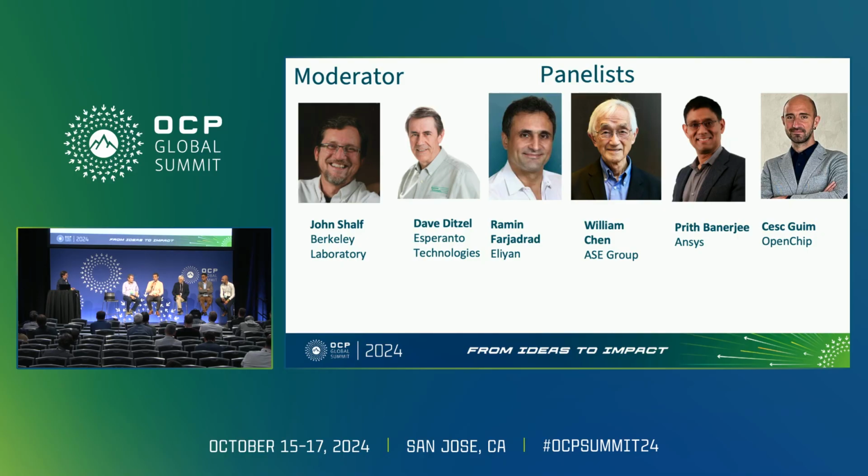But as Dave mentioned, for everything else, people try to do it internally. Not necessarily because it's not possible to have these standards, like UCIe or BoW, but sometimes it's more of an economic or business reason. Companies that, let's say, do the ASIC say, I have to provide the D2D on both sides, otherwise I cannot guarantee that they work.